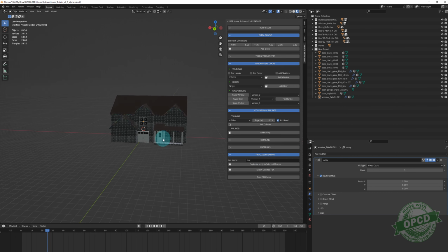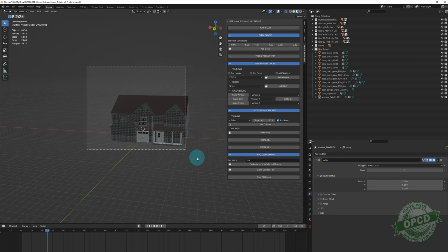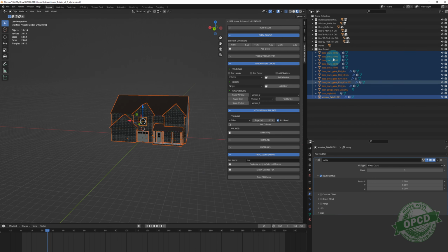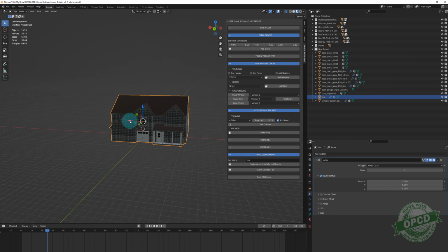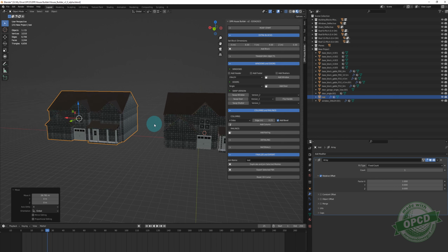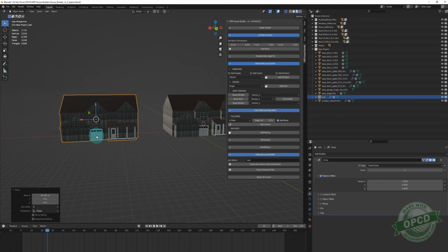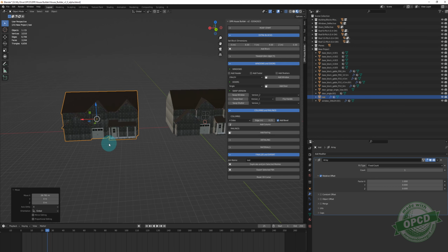When you're done with it, you're going to want to select everything. So I put this in X-ray vision, left click and drag select. See how this is a new project here? It put all the pieces in the new project. Then you can duplicate and join selected meshes, and that's going to give us a single piece. So now you could always go back and edit it if you wanted to, but now you have the single piece ready for export into Unity. So it's a single mesh.